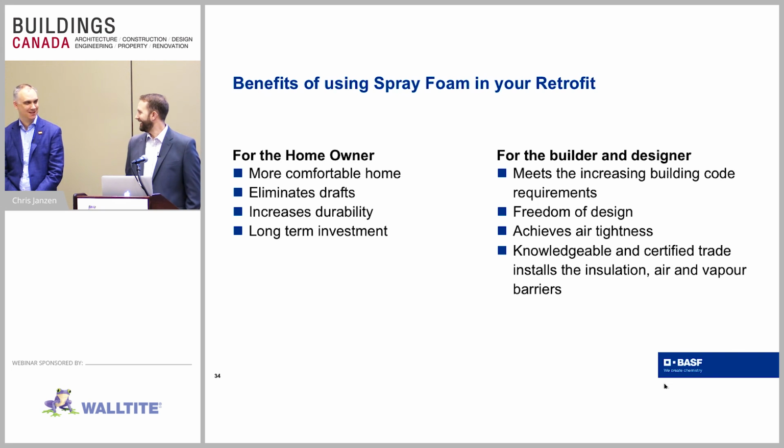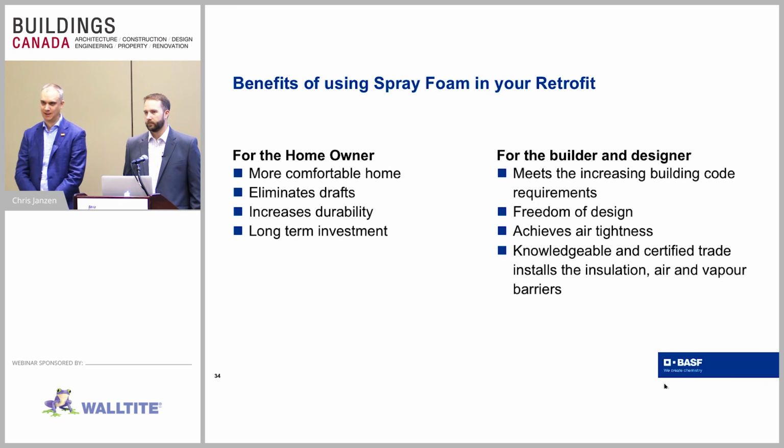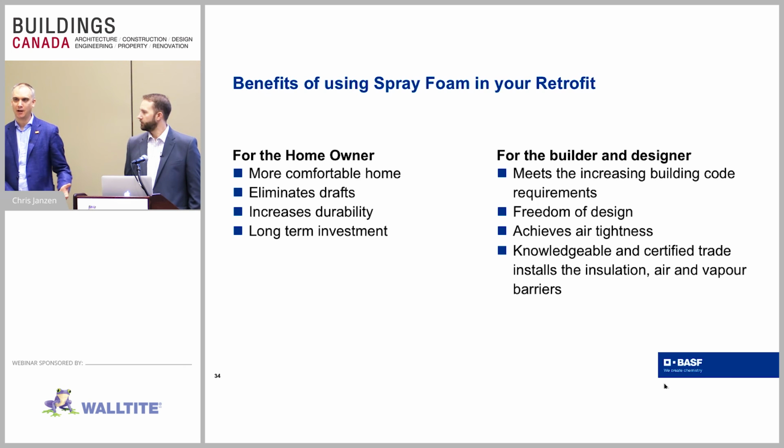Well, open cell is going to be comparable because it has very similar properties to a rock wool. Closed cell foam is going to transfer sound through it a lot more, but it locks everything down, so it stops those rattlings and the lower rumbles. Let's say traffic noise or something like that, it's going to quiet a truck driving by, but it might not quiet down somebody talking.